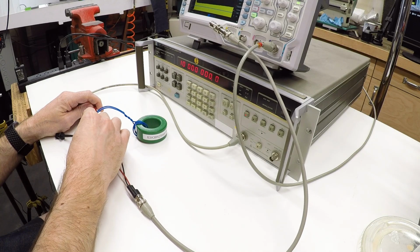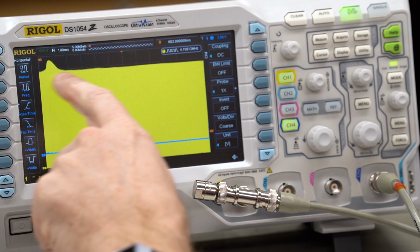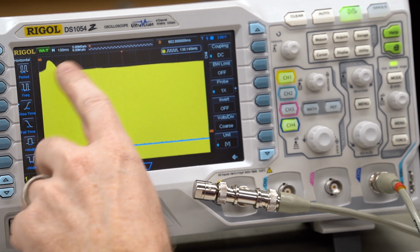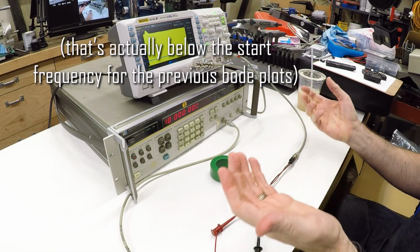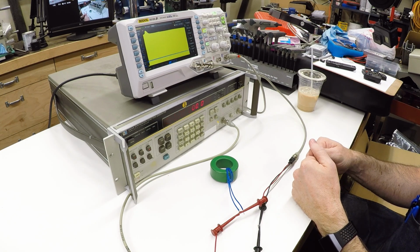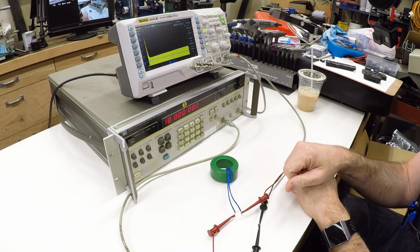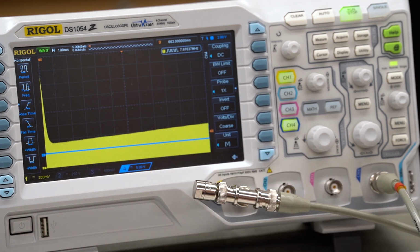Now if I take it out of circuit, just short across it here, you can see that we get a mostly flat frequency response. I honestly don't know what's causing this little peak here. Something is resonant at that frequency and the gain is higher or the loss is less. I don't know, maybe somebody who actually knows more about this stuff can chime in the comments and let me know why that is. But if we look at it with the coil in circuit, we can see that the low frequencies are passed and then the high frequencies are attenuated.